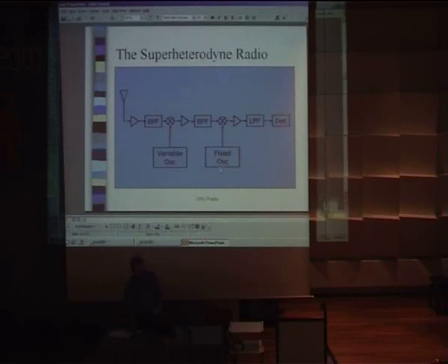And then what you end up with is usually another fixed oscillator that's just going to knock the signal down. This is a fixed signal, this is a fixed place, plus your signal riding on it, and this usually knocks it down to some other place. And then on the back end of this thing, there's some kind of what we call a detector, but it's really where I'm going to look at what comes out of here and say, is this analog? And maybe here's my radio signal, my broadcast radio signal, audio-wise, and my FM signal.